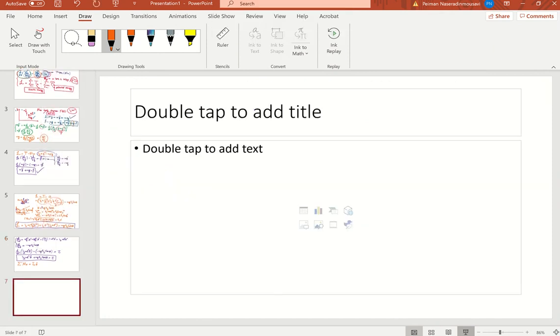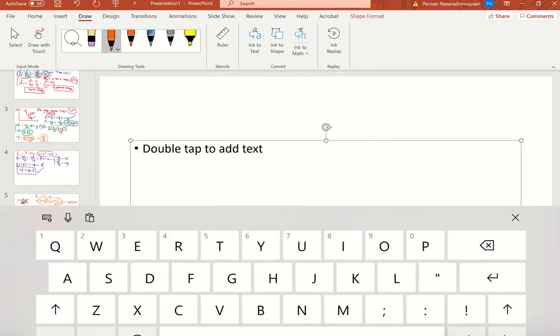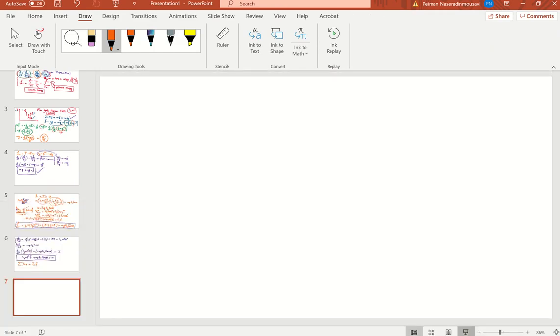Listen. Now the question is, if I have an n degree of freedom robot, how do I develop that? As I said, this is the Lagrangian equation: d/dt of ∂L over ∂q dot k minus ∂L over ∂qk is tau k.